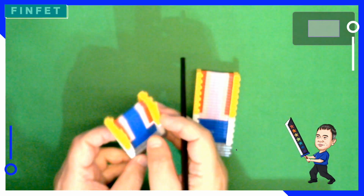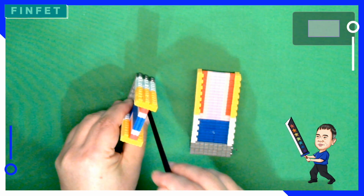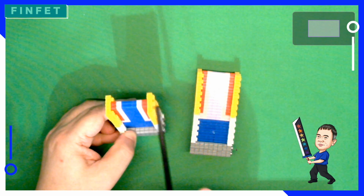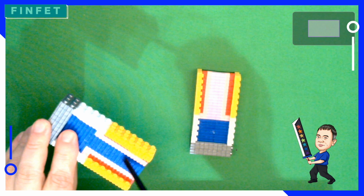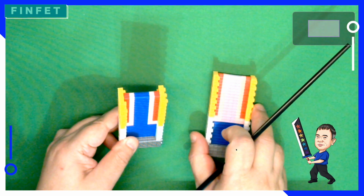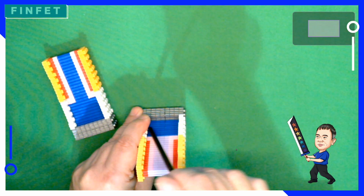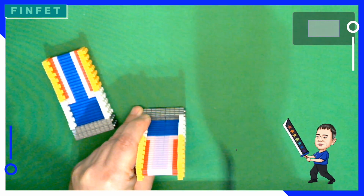So next one is a FinFET, F-I-N-F-E-T. FinFET means the channel itself looks like the fin on the fish's back. And here is the source, here is the drain, and the control gate, source to drain. So this whole thing, the blue part, is the channel. And this substrate doesn't carry any current. It's also possible your fin uses a different material compared to your substrate here. The fin uses a different material, with a different color.